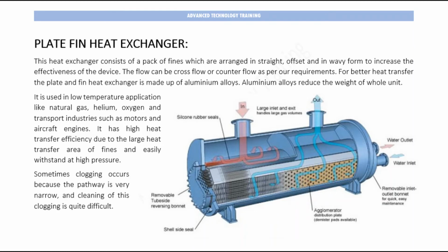Plate fin heat exchanger. This heat exchanger consists of a pack of fins which are arranged in straight, offset and wavy form to increase the effectiveness of the device. The flow can be cross-flow or counter-flow as per our requirements. For better heat transfer, the plate and fin heat exchanger is made of aluminium alloys. Aluminium alloys reduce the weight of the whole unit.